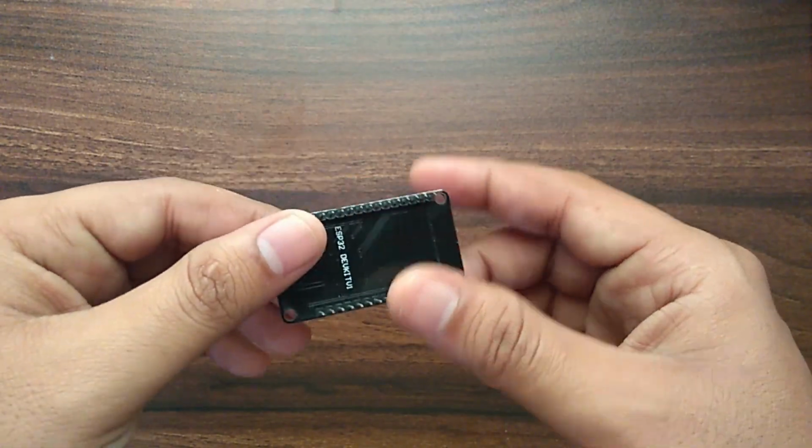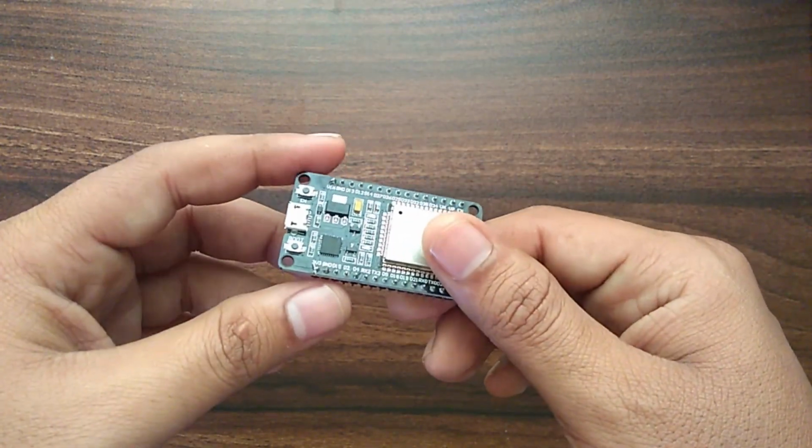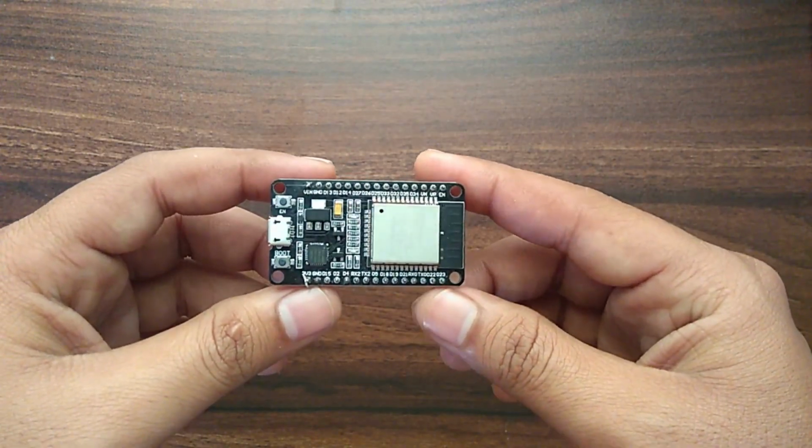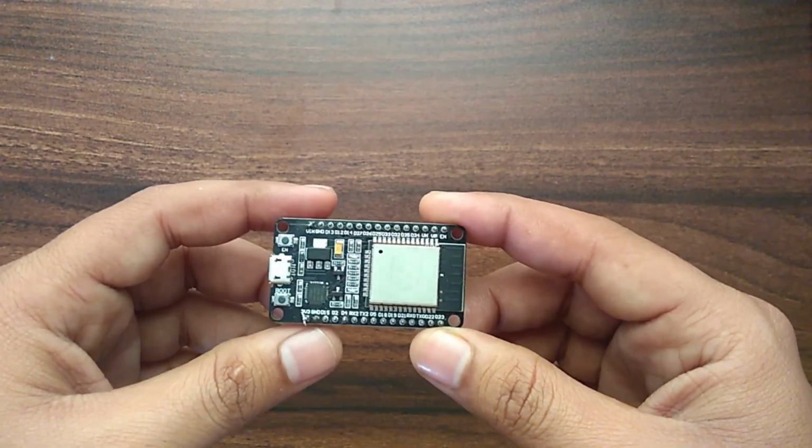I had two choices to select the Wi-Fi module, but I preferred to go with ESP32 because it has many ADC pins and sufficient GPIO pins. One more point to note is that Wi-Fi and the ADC2 channel don't work together in ESP32.